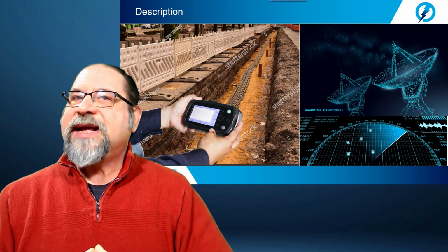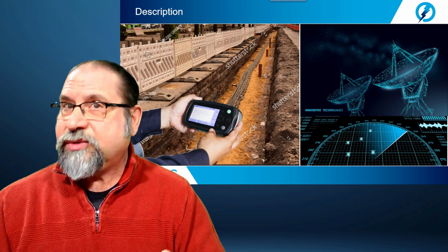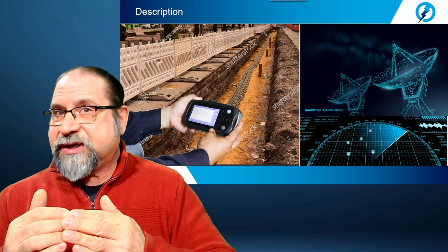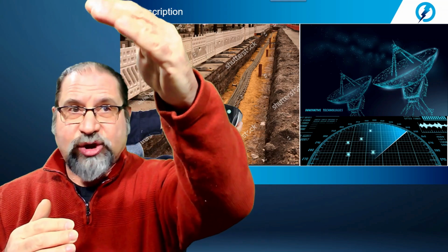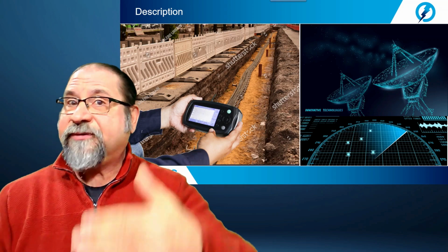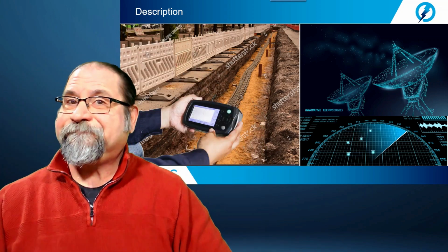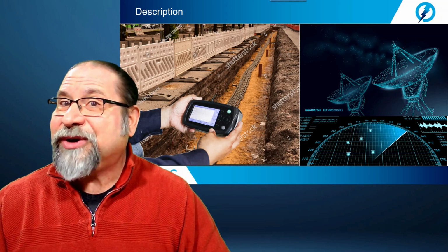As we can see, the time domain reflectometer is very similar in principle to conventional line-of-sight radar, where, as we're aware, a high-frequency pulse is launched or transmitted out. As this pulse propagates, it travels and travels until it encounters a physical object, for instance, an aircraft. The pulse reflects from the aircraft and returns back to the source. This is very similar in principle to the way the time domain reflectometer is operating.